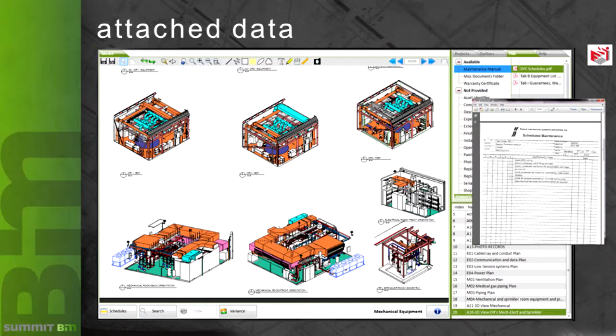You can attach any information to any object within the BIM database. I can attach a video which tells you how to maintain that particular object. You can attach all the shop drawings, warranties, Word documents, Excel documents, whatever you want to that particular object. You can colour it to see whether or not it's got a warranty on it. All that information is easily done.